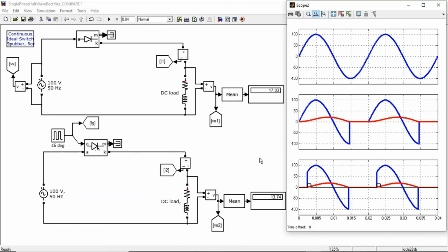As we can see here, the extinction angle increases along with the impedance angle. Hence, it verifies the relationship between the impedance value and the extinction angle that we have discussed in the previous topics. Lastly, as similar as we did to the uncontrolled rectifier, we can increase the average output voltage of the control rectifiers by using a freewheeling diode.